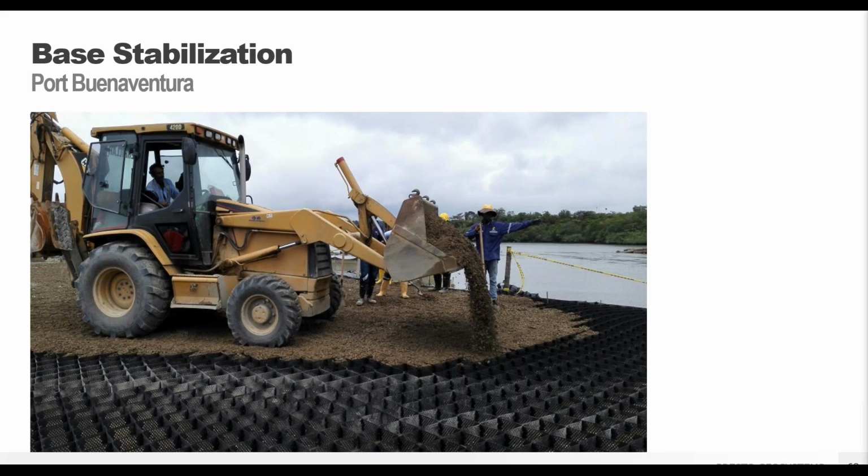So our solution this time included a 6-inch GeoWeb panel and local fill material. And since the GeoWeb was able to reduce the stress on that subgrade, we were able to reduce the depth of the pavement from 8 inches to 6 inches, so a 25% reduction. That comes out in total cost savings for the owner in the end. Everybody likes that when you're going for value engineering.